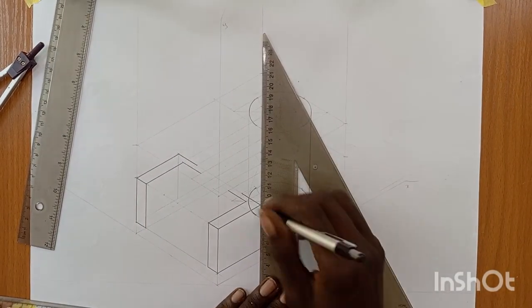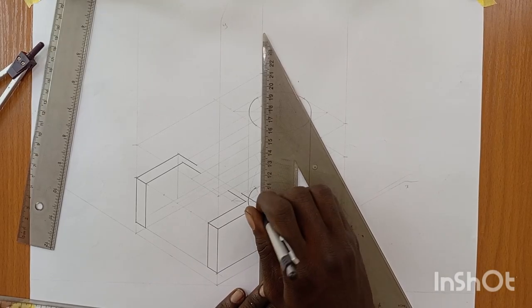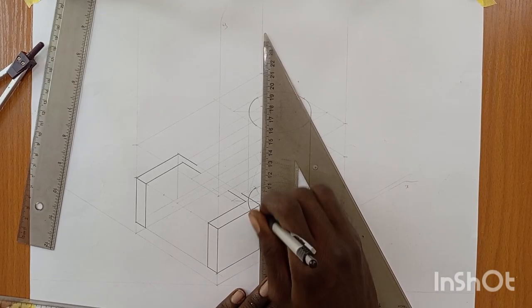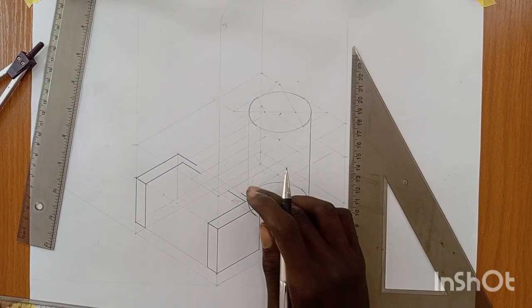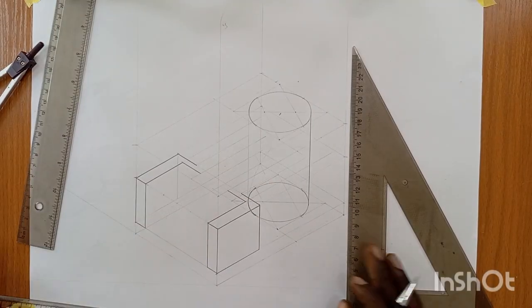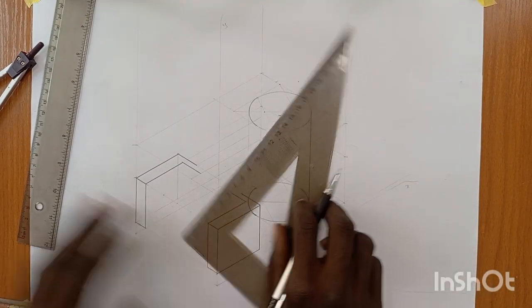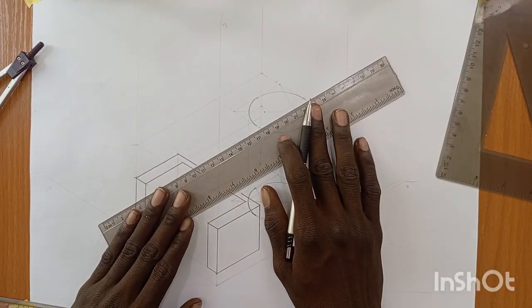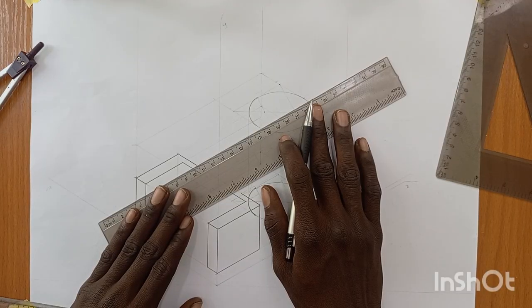You see, this is the reason why we see the base of the cylinder, we draw our lines in construction line. You can see the base of the cylinder is covered. Those lines here. This one, which I didn't make darker, is going to be covered. So now, the next thing to do, you can make this one also darker. Make this dark.